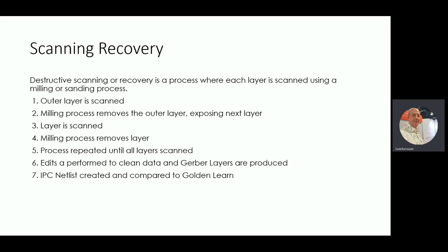And then once all that's done, we tell the system again to recreate the intelligence. So it takes all of those photo layers, and we send that into CAM software, because we've created the photo tools or the Gerber layers, and we can take that into a CAM system and regenerate a full netlist photo tool set where you already have the photo tools, the drill files, and even a netlist intelligence.